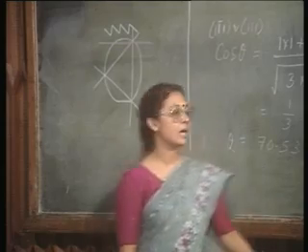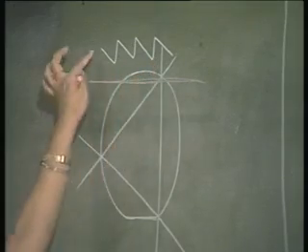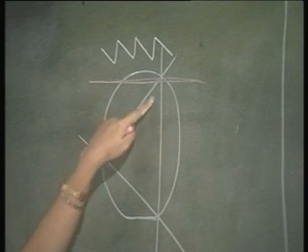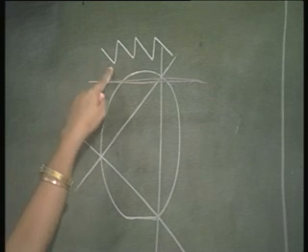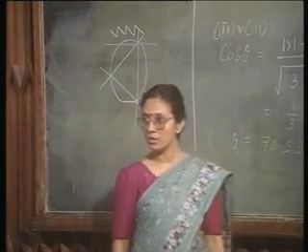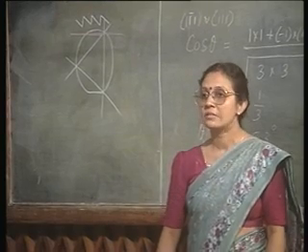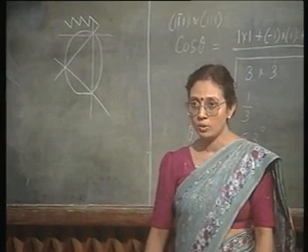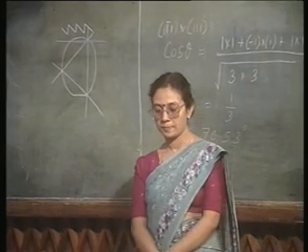Instead, you are going to have a fine zigzag pattern with each line referring to this 110 or this 110 lines, right. That is what I meant, each zig and each zag corresponding to 110 directions. So, it is a bit difficult to cleave the 111 wafer in mutually perpendicular direction.